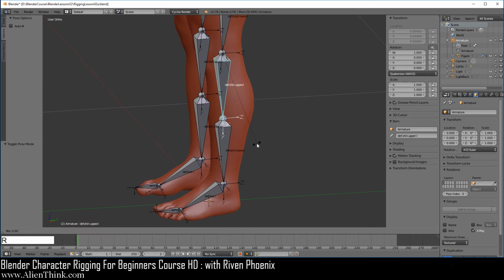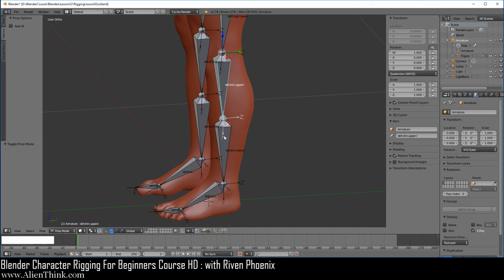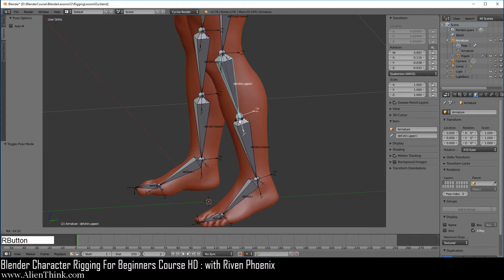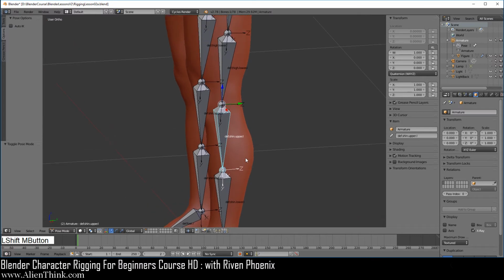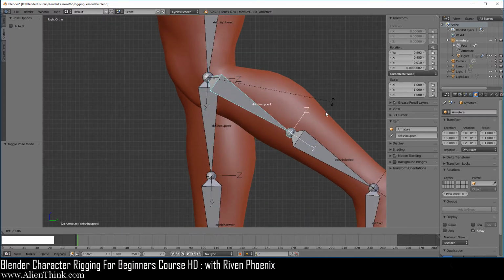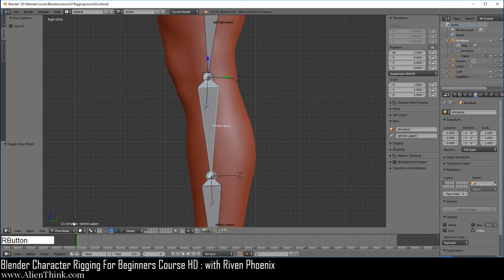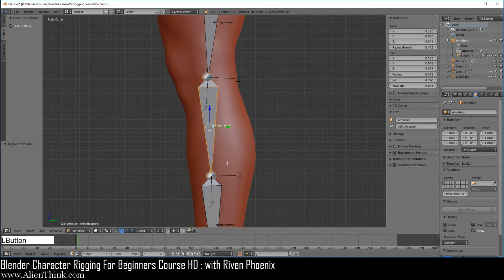If you press the R key, press the F key 2 times, this is how the knee bends. So this bone is going to follow what this bone does. So here you can see that the Z is pointing back. So this is correct. Over here, if we click this, you can see that the Z is pointing back. If you press the 3 key to look at this, press the R key, here we're bending on the knee, right? So the Z is pointing back. And if we take a look at its bone roll, you'll notice that again, it's negative 1.24, okay?